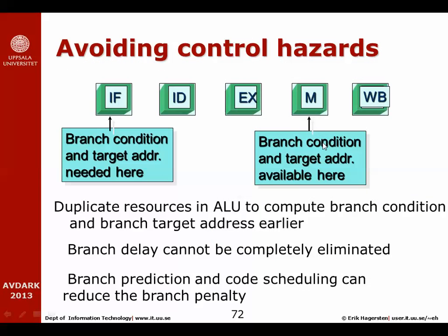So one way to do that would be to do a more aggressive design. So we're going to design this with hardware. The problem in hardware, once more, is that the outcome of the branch has to be known at the instruction fetch early on, so we can fetch the very next instruction, be it A or be it E. The right instruction has to be fetched right after the branch instruction has moved on. But we don't know the outcome of the branch until much later.